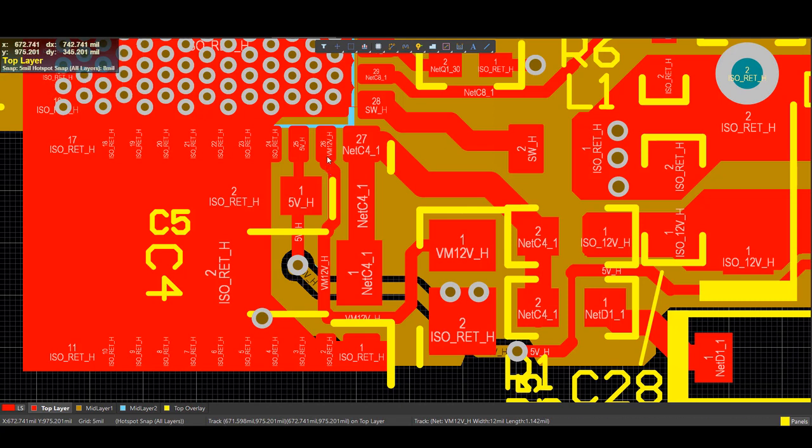Next, let's take a closer look at the power stage bias supply and control bypass capacitor. Recall that the priority is given to the VNEG bypass capacitor, which supplies the gate of the FET. Looking at pin 26, which is the VNEG pin, the bypass capacitor is far away with a long wire connecting to it. The inductance along the path will make the supply to the gate very unstable. Also, the position of the VDD cap at pin 27 could also be optimized.